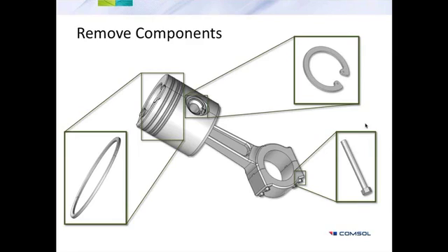At a first approximation, we would remove a lot of parts that are not necessary to give us answers, and might remove the retainer ring shown in the upper right corner of the slide, or some of the O-rings that sit around the piston. We might just fill out the space with the material properties, but incorporate it as a much simpler domain in the analysis itself.